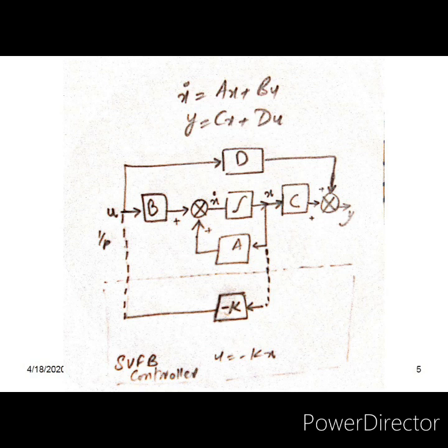But at the moment, this portion, the integrator, the left summer, the matrix A, and then we have the B matrix, is the implementation of the state equations. u comes from the left hand side and goes into the B matrix and then goes into the summer, and then we have x multiplied with A and then goes into that summer. The summer on the left hand side becomes the derivative of the state vector.